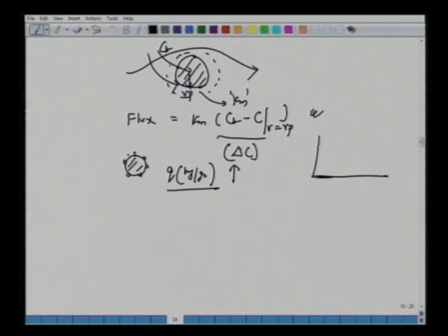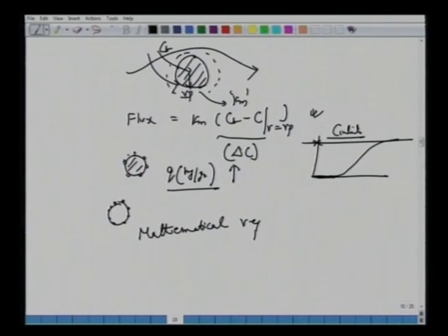For a lot of time you don't see any exit concentration. Why? Because the solids were fresh, they were adsorbing species until the solids start getting saturated. On the surface, no more sites are left. Then we have saturation, and all your exit concentration has reached the inlet concentration. So this is your physical, pictorial representation, which we would like to represent by mathematics here. Mathematical representation.